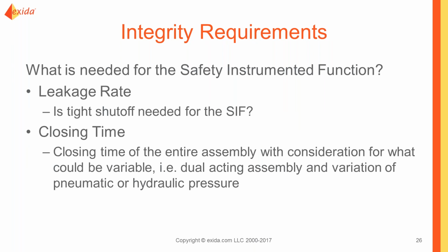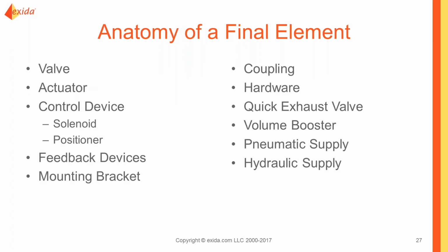Integrity requirements are going to be how well does it need to work. So the functional requirements are what is the function, what's it doing, and then integrity is how well does it need to do it. So leakage rate is an example of how well it needs to seal. Closing time is important on most SIFs because it's essentially how quickly will that final element bring you to the safe state, or if it's a motor, how quickly does that stop spinning down? Is there a lot of inertia in the motor that's going to continue to drive stuff even when you de-energize it? Similarly with the pump. So understanding those conditions is important.